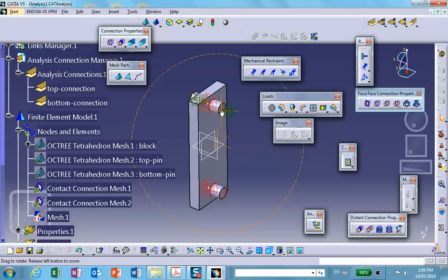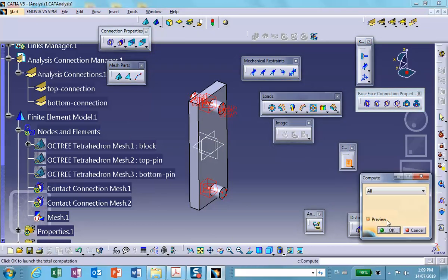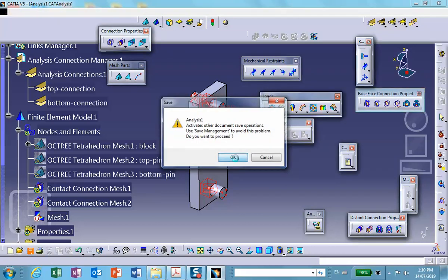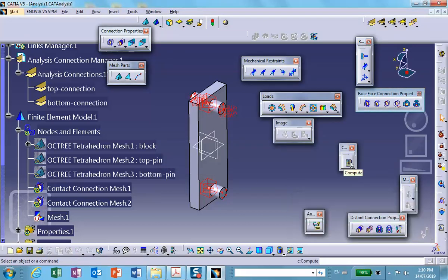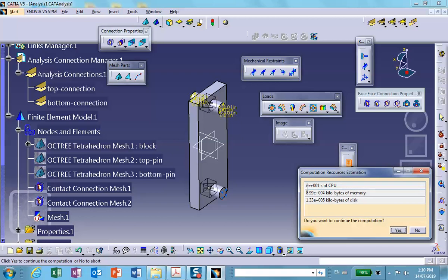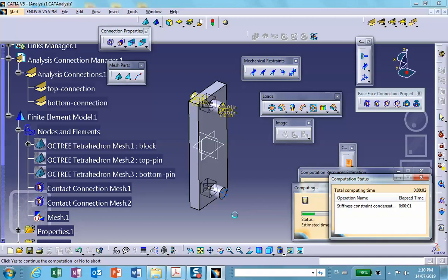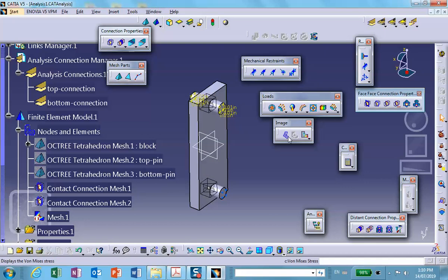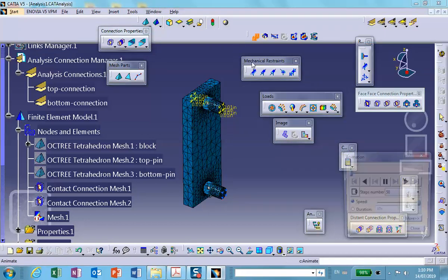So let's run it. I should have saved this thing. Where's the save here? Save. This is in case I have to stop it. Then at least we don't lose any of the stuff that we have done so far. Okay, this will be fast. By the way, look, from 2000 it went to 20 because of the linear type. And let's run it and watch that it miserably fails. Okay, let's see what happened now. So plot the deformation and animate it. This time, the block, nothing stops the block from moving.